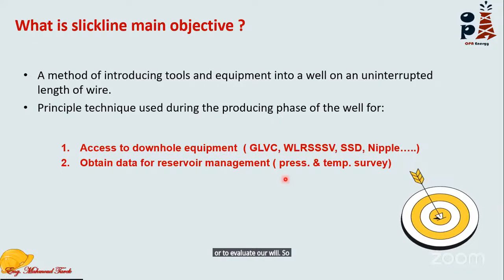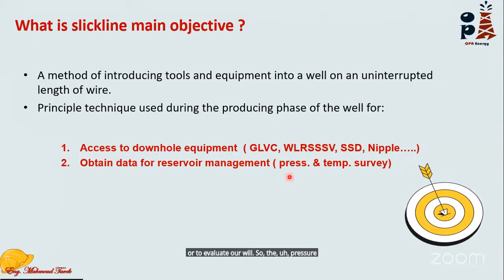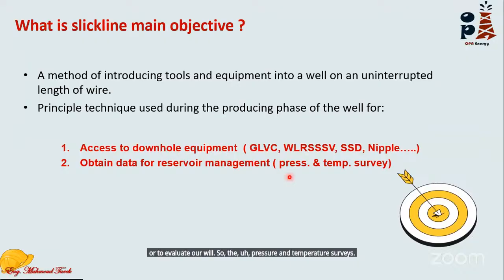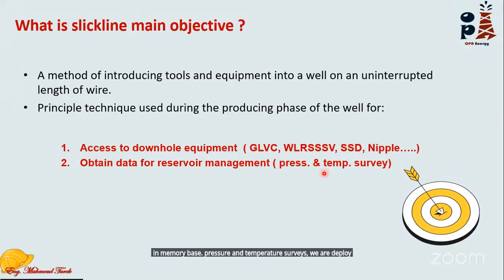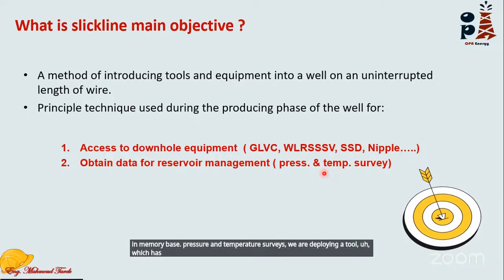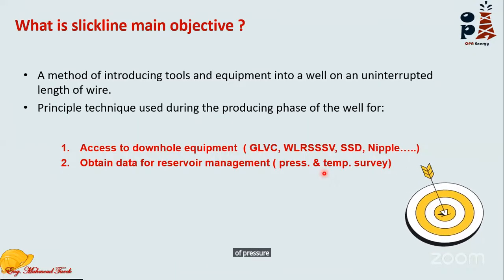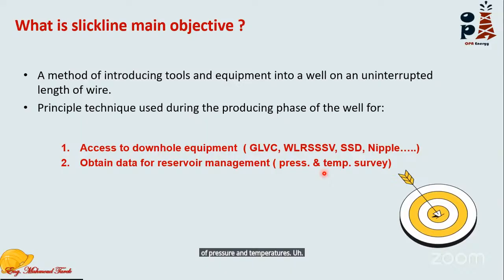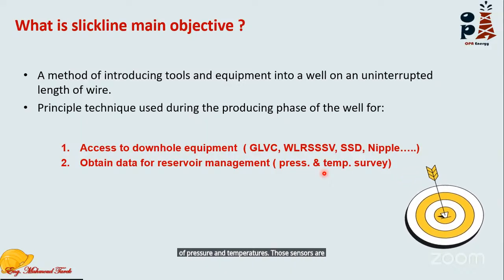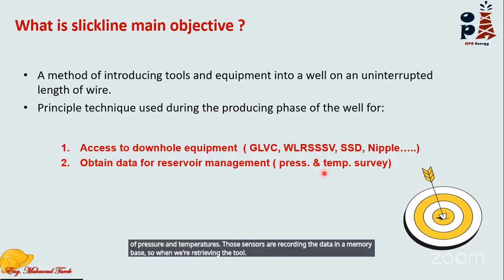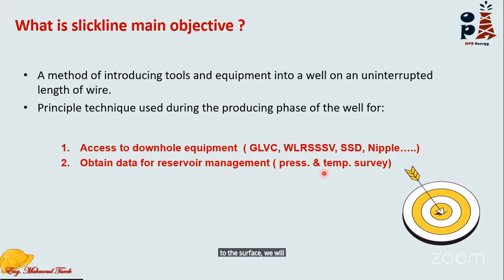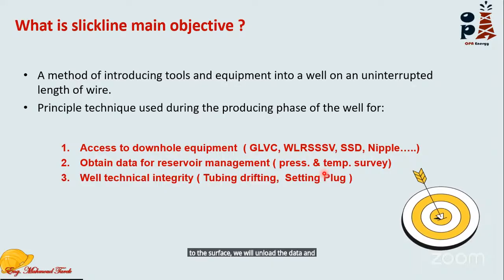So, pressure and temperature surveys in memory base: we are deploying a tool which has sensors of pressure and temperature. Those sensors are recording the data in a memory base. So when we retrieve the tool to the surface, we will unload the data and analyze it.